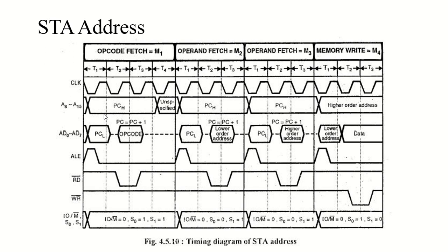The first machine cycle, as you can see, will be opcode fetch, and I'm not explaining the whole cycle one more time because we have done it around 7 to 8 times now. In simple language, the program counter will place the address on the higher order address using the H register, and on the lower order address using the L register. The cycle will fetch the opcode from program memory using the program counter during the T2 and T3 states, and then the program counter will be incremented by 1 and move to the next instruction. Now the opcode for this instruction will be 3AH.